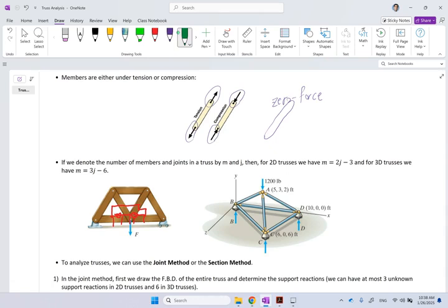So let's say the equivalent force is right there. And then again, that equivalent force has to be broken down between these joints. So if it's applied to all of this bottom portion, then maybe each one of these joints is taking a portion of it, depending on how close they are to that weight, right? So the closer they are to it, the bigger portion of the weight they are carrying. As I said, inversely proportional to their distances from the joints to that equivalent force.